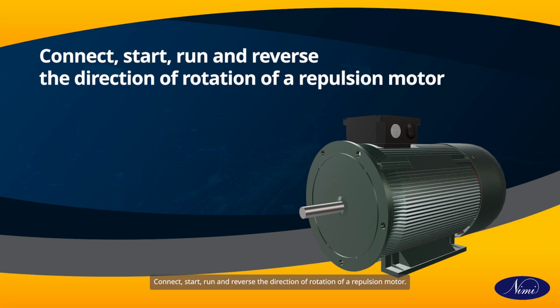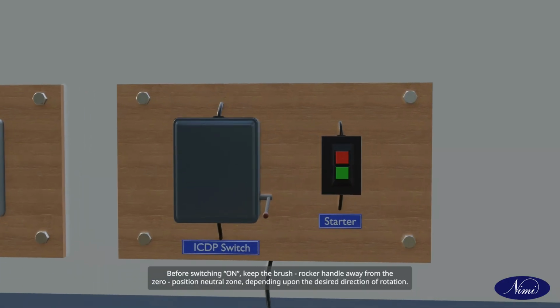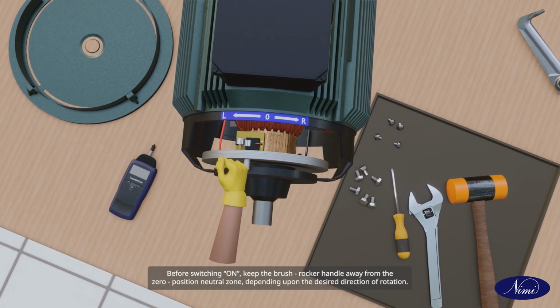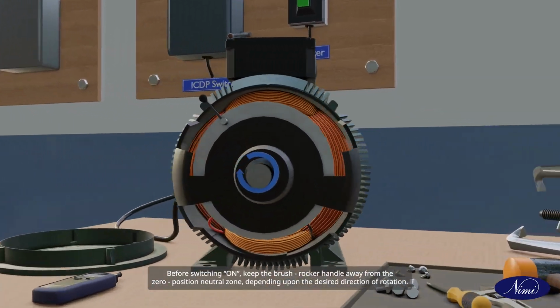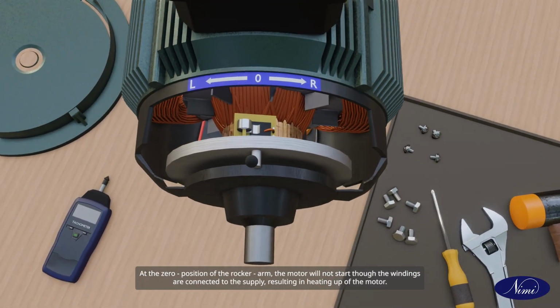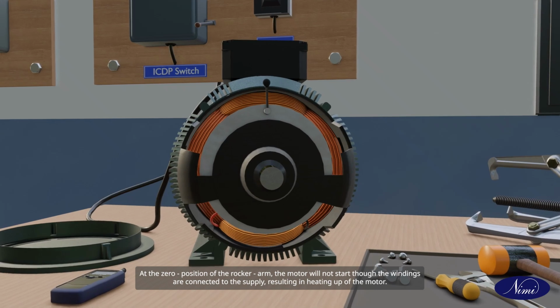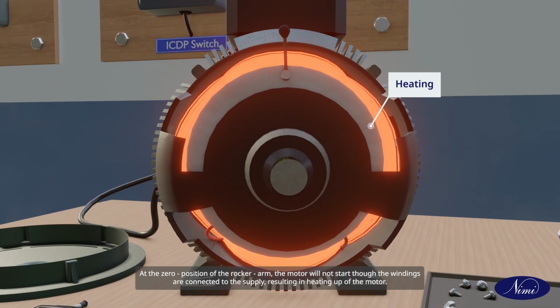Connect, start, run and reverse the direction of rotation of a repulsion motor. Connect the devices in accordance with the circuit diagram. Before switching on, keep the brush rocker handle away from the zero position neutral zone, depending upon the desired direction of rotation. At the zero position of the rocker arm, the motor will not start though the windings are connected to the supply, resulting in heating up of the motor.